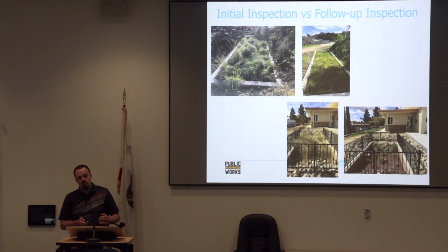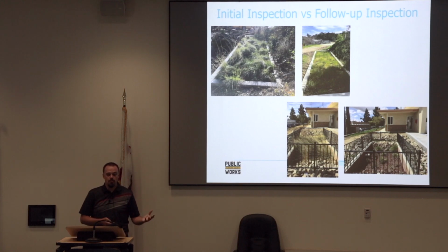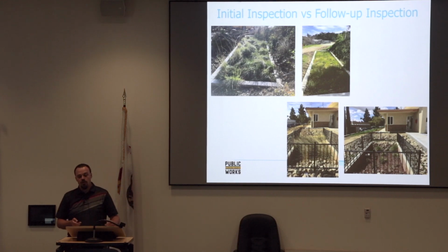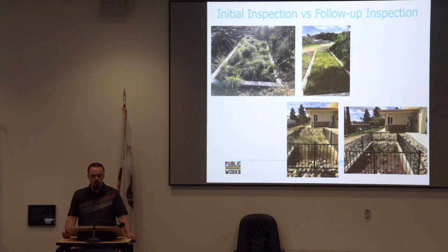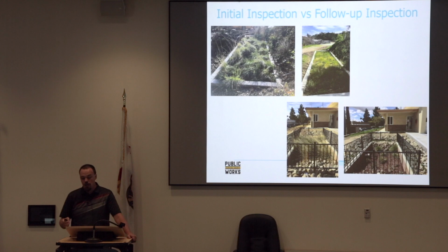Here's a couple more. This is when we went to an inspection first. Both of them are different bioretention systems. We have the first one at the top, obviously overgrown. You can see all the vegetation is folding over. It wasn't draining properly. Once they went in there and did some minor sediment removal around the inlet and then cut the grass, it started draining fine.